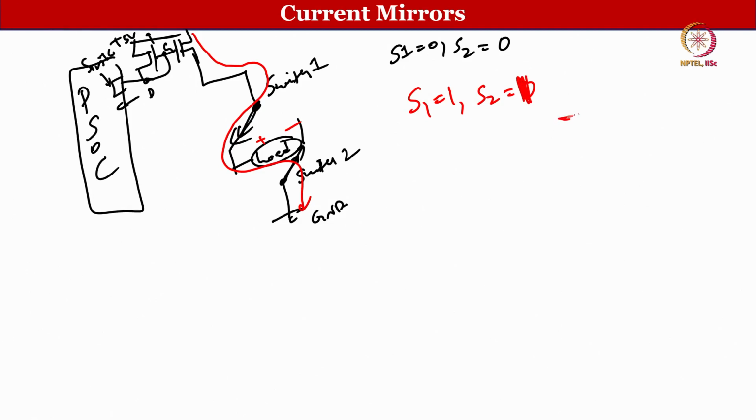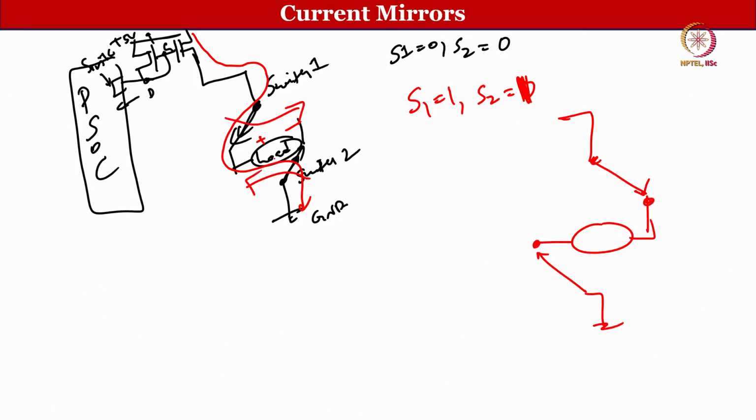That means that you have a switch here which connects like this and there is a load and now the switch will connect back to this, because switch positions have been changed like this, right, and these are analog switches, okay. You can just program them and then accordingly it will switch. They are also called SPDT switches, single pole double throw switch.